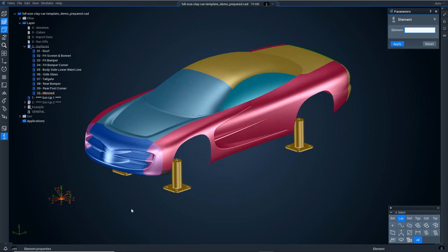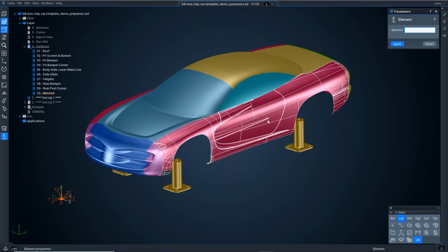What you'll also notice is down in these corners, we have a series of axis systems. Now the green axis system is our datum for machining the actual part. The red axis systems are going to define tool direction. So when we come down the side of the car, we're going to need a tilt angle on this. What we can see is the Z direction is going to denote the direction of the tool.